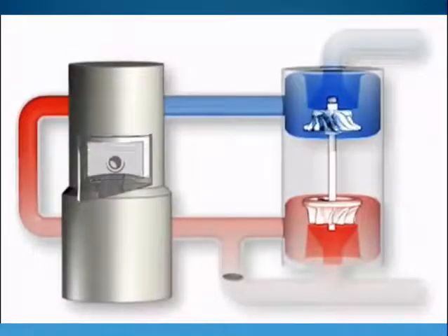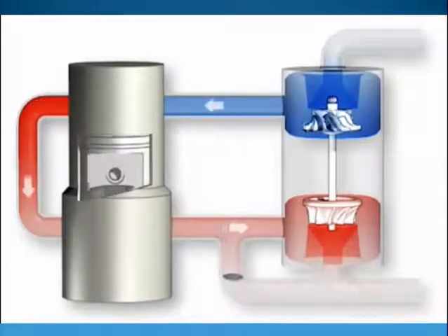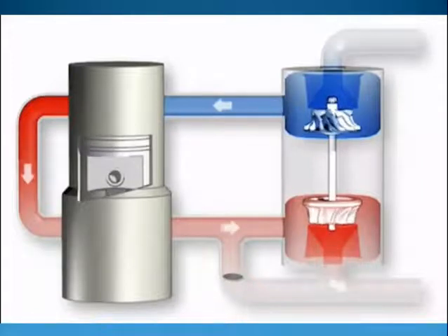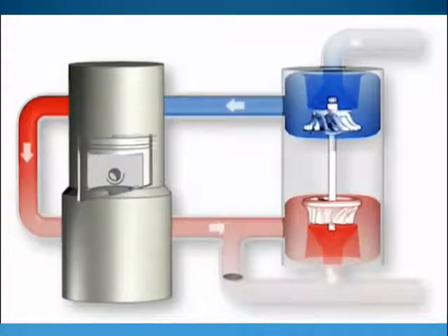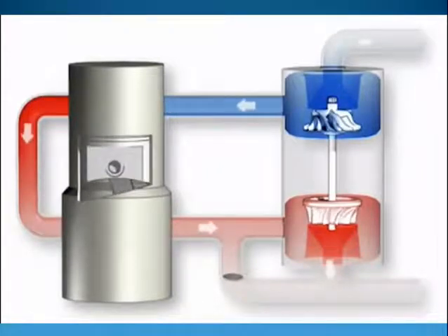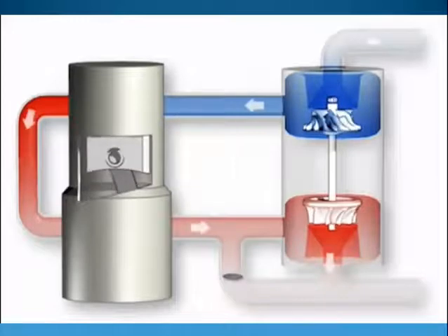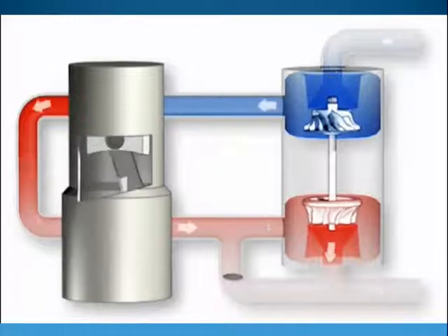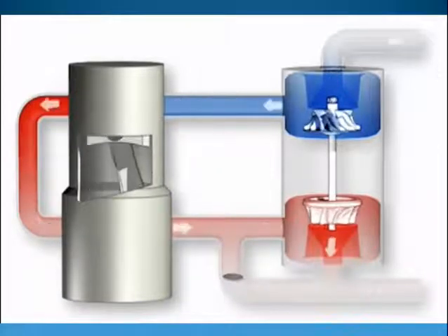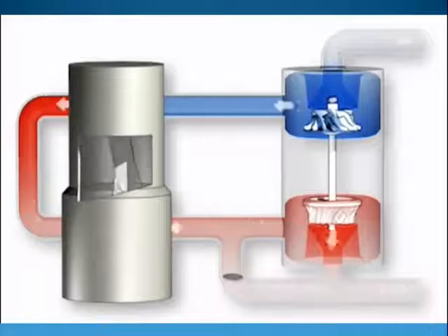Charging pressure control. Today, the charge pressure is normally controlled as a function of the turbine output or speed of rotation. An increasing charge pressure is accompanied by increasing speed of rotation of the turbine. The turbine output or speed of rotation is dependent on the available exhaust gas for the turbine. Small turbines are used to achieve a corresponding charge pressure even at lower loads. However, this small turbine is no longer able to achieve throughput of the exhaust gas quantity at full output. A bypass of the turbine is required in order to relieve the situation.